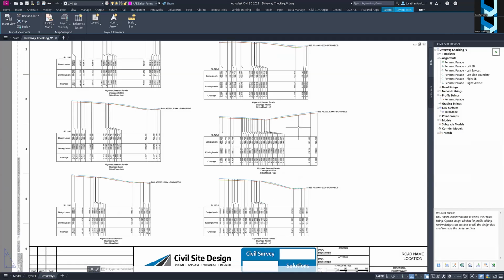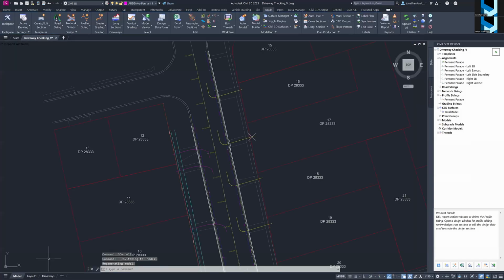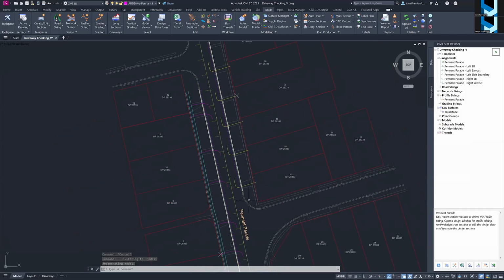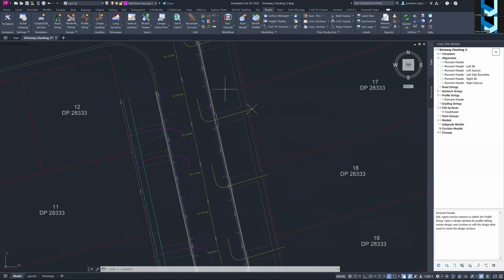of your design checks. And you can see within the process of well under an hour, we've gone from, other than just having a design, we've been able to check quite a large number of driveways in a very short space of time, review the criteria that's applied to them, change the laybacks, also look at the left-hand side, apply an optional outside shape, then introduce a layback into the design, which once you get into the hang of using that particular variation, it's very, very quick.